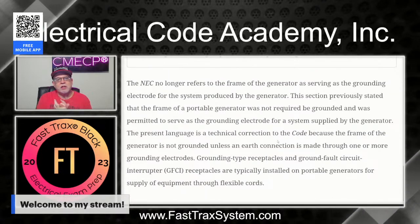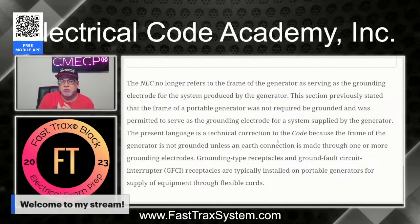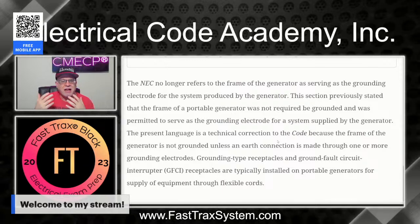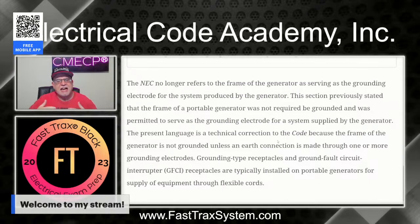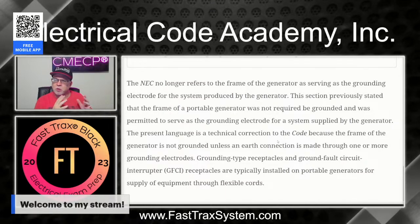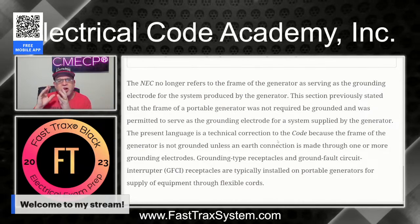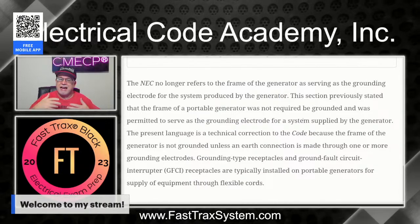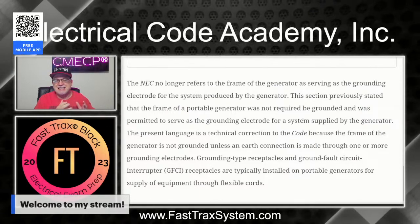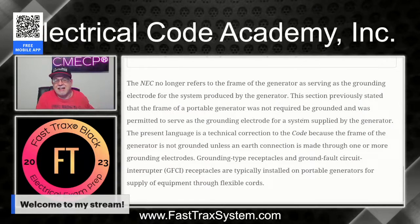Now, remember, we're looking at the 2023 edition of the National Electrical Code. And why is that important? Because there was a change in terminology and technical jargon and how we explain something. Let me read it to you and you'll get a better understanding, especially if you're in the 2020 or 2017 edition and you see us doing this in 2023. You're thinking, isn't that metal frame acting as an electrode and that's why we don't have to have an electrode? No, it's not, because that frame is not connected to earth, so it is not an electrode.